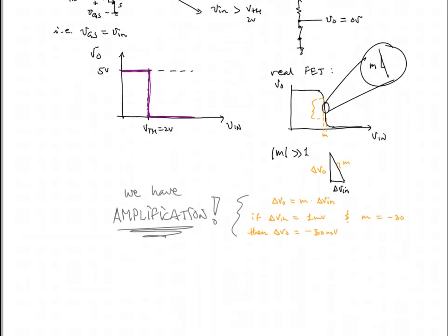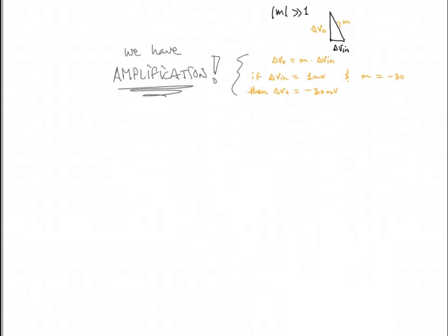The last thing I want to mention before closing is one augmentation to our model. Not one that will allow us to study the transistor as an amplifier, but one that gets us a little closer to a real transistor model. So let's look at what's called the SR model. What do you think the R is for? Just like our diode, remember we had our Shockley equation. Well, first it was a 0 volt diode, then a 0.7 volt diode, and then we said we can add a constant slope, we can add a resistance in series with our constant voltage diode.